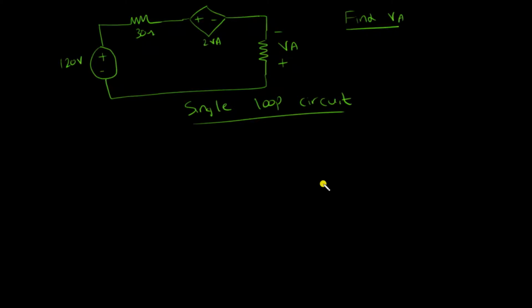In this lecture, I'll show another interesting application of the KVL. If this is a loop, it is called a single loop circuit because there's just one closed path, or just one loop. Whenever I see a loop, I know that there is some KVL being applied. So I'll write applying KVL, and by convention I always move clockwise.